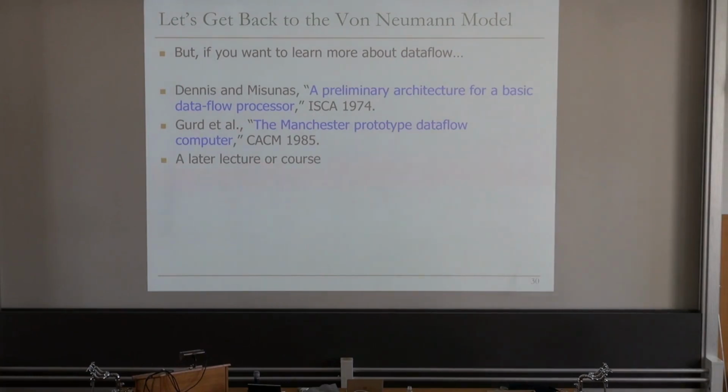Today, I think it's easier because of FPGAs, for example. But at that time, the paradigm was, if you think about it, very single core, sequential. So that paradigm actually engulfed the data flow paradigm, if you will. What happened was you couldn't change the ISA to be data flow, but internally, you could change the microarchitecture to be data flow. As a result, you got the benefits of the data flow while keeping the interface sequential. But of course, the benefits may not be as high as what you would get with a pure data flow machine, right? So it's a trade-off.